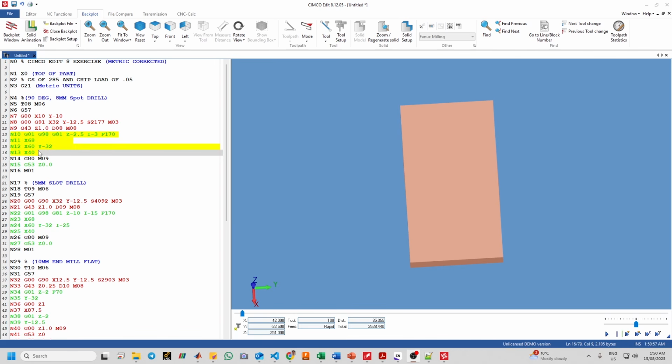Okay, now we see some green lines. These green lines are inside the drilling or canned cycle, for example G81 or G83. But let us check this line. So G01 normally means linear cutting, but I think here it is paired with a cycle command. Which one is the cycle command? So G98, I think. G98 returns to the initial level after each hole.